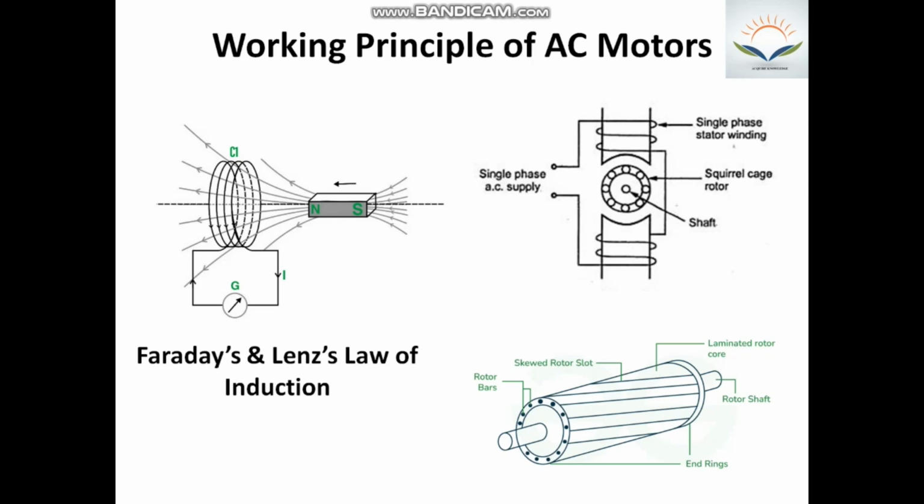The magnetic field generated in the rotor as a result of the circulating current adheres to Lenz's law. Lenz's law states that an induced electric current flows in the direction such that the current opposes the change that induced it. Thus, the field generated in the rotor will oppose the one produced in the stator. This leads to the rotation of the rotor assembly.